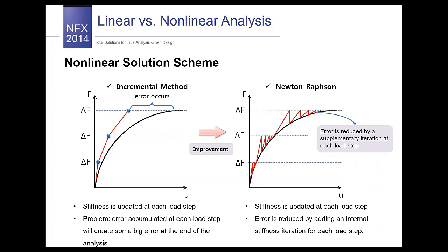Both of them present an incremental method to obtain an accurate solution and satisfy the modeling conditions. And the basic idea of this incremental solution sounds like this: the total nonlinear response of the system can be replaced by the sum of linear responses which come from incremental loading.